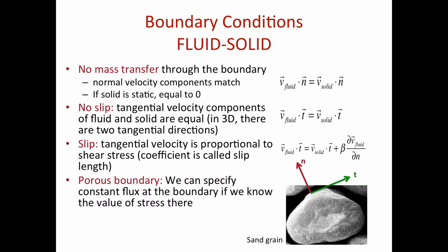This is often for those of you who are going to work in fractured formations or modeling fractured flow. Typically, you have a similar situation near the fracture. You have rock matrix, and you actually have to specify what is the transfer across that boundary for all of the fluids involved. And that's not necessarily easy, and of course affects your overall solution a lot. And those are certain assumptions that you often have to simply make. Okay? So beware of the boundary conditions. Again, they can change your solution a lot.